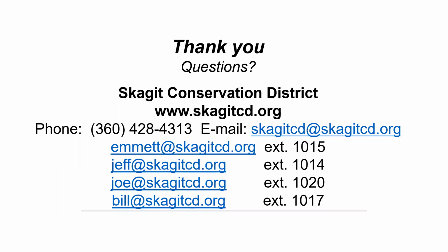And somebody asked, what is a dry well? Usually it's an area underground that you've excavated and put in gravel or coarser material, and then you're diverting roof water, gutter water, or something to that area because you have nowhere else to go with it. And usually the soil type is a certain kind so that it disperses once it goes there. So once it's holding, it's kind of like a septic, but it's just for regular water.